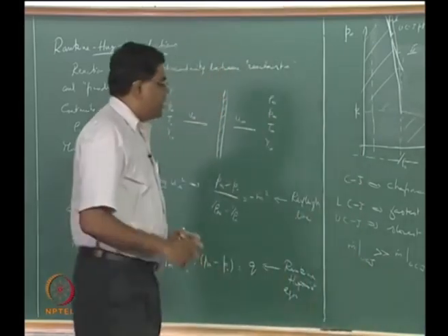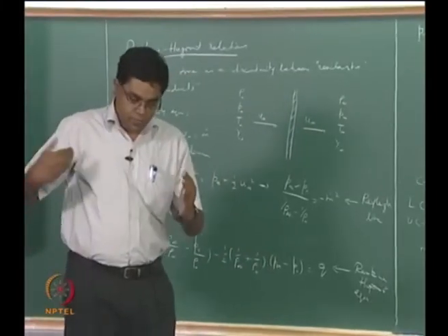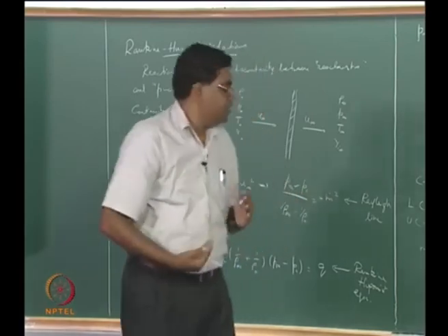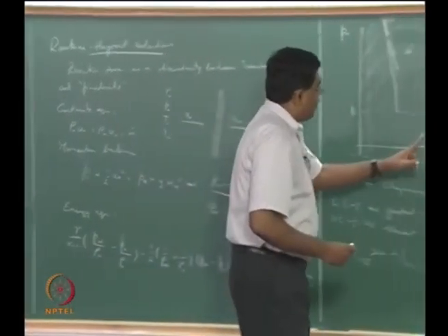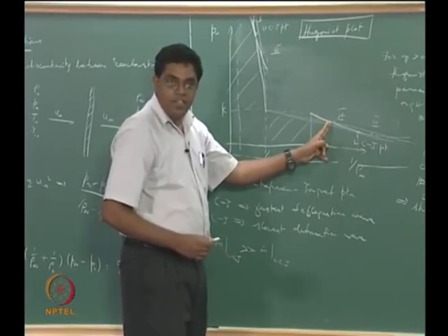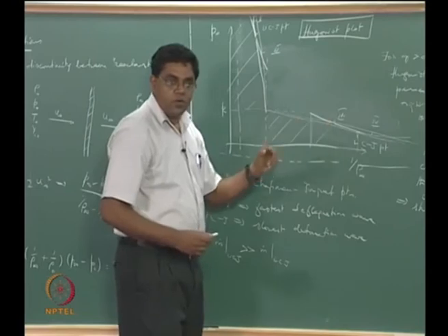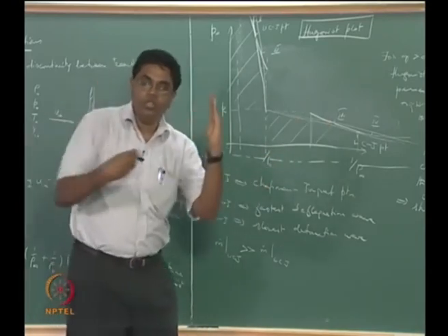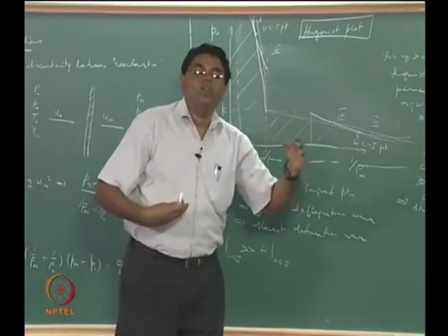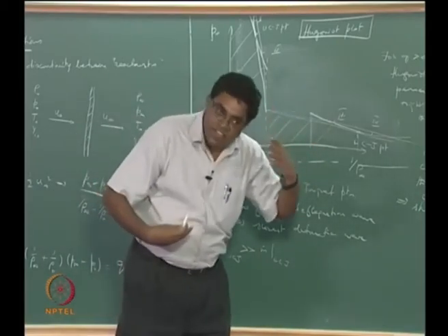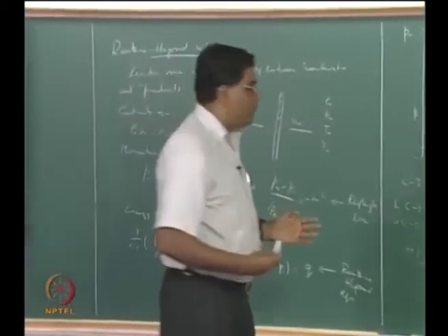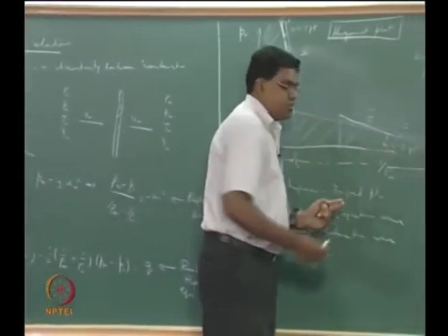So when you now have a deflagration wave, the flow accelerates when it goes past it because it is expanding, right. Now while you are here you are not expanding a whole lot, and that is because it is a weak deflagration, and therefore you started out with the flow approaching you at subsonic speeds and you are accelerating to further faster but still subsonic product speeds. That is the mark of weak deflagration.